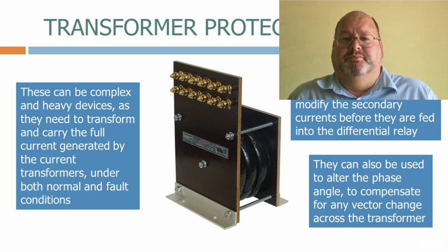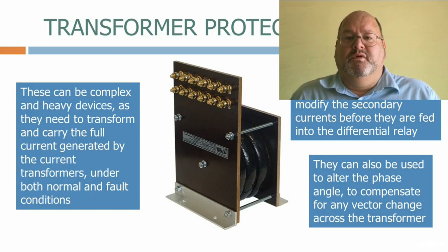The unit protection principle is a very powerful one, which compares the phase currents going into a device with the phase currents flowing out. If they are both equal, then we know we have no faults on the device being monitored. As this is such a simple philosophy, unit protections are very reliable and can detect a fault on the equipment very quickly, something that is essential when protecting such an expensive device as a transformer.